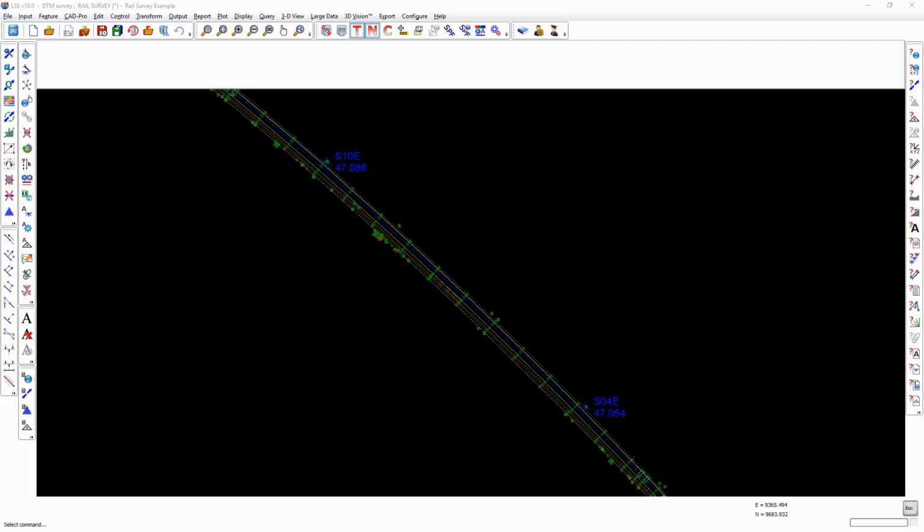For surveyors using EDM, GPS or a combination of TMDs or track measuring devices, there is usually a maximum permissible distance that any single survey point may be observed from any station setup. Therefore, repeat measurements from the next survey instrument setup need to overlap with those from the previous one. It is the comparison of these overlapping points and the subsequent averaging of their positions which is the purpose of the Rail Overlap command.